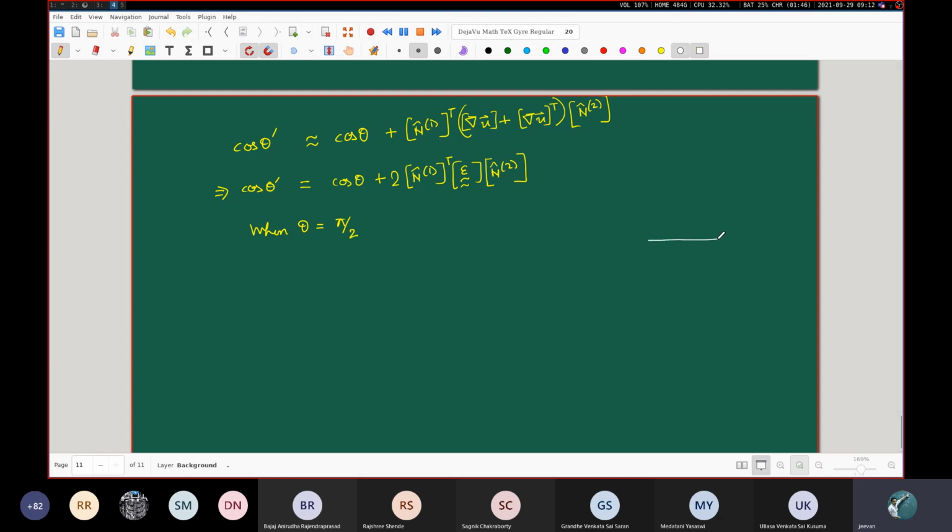The picture has now become like this: you had originally your P and Q like this, and your P and R like this. So this angle was theta equal to pi by 2. And now in the deformed configuration, this has become P dash, Q dash, R dash. This has now become theta dash. But can we not write theta dash in terms of this original theta? Can we not imagine that theta dash is equal to pi by 2 minus gamma, because we know that these two angles together, this is gamma.